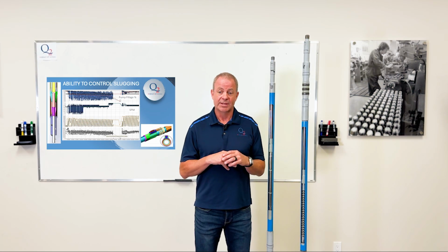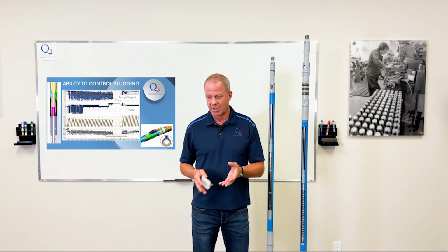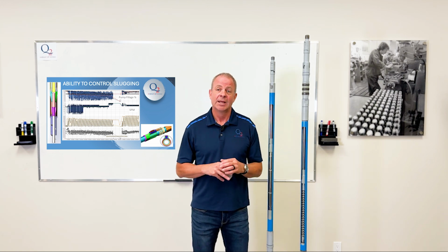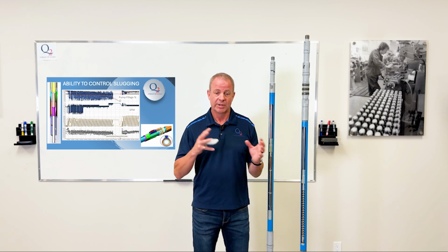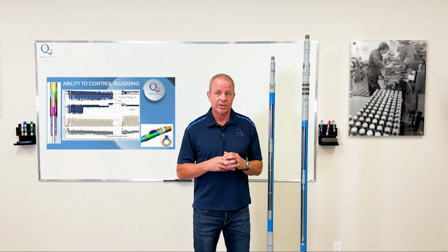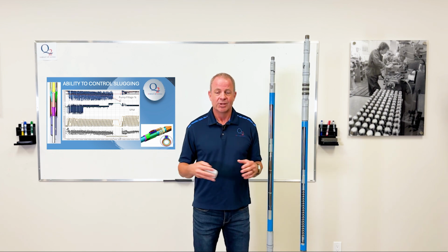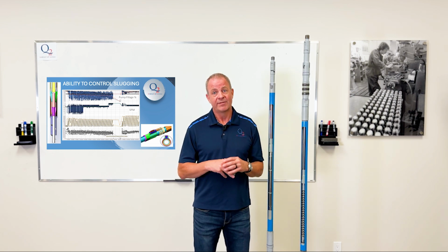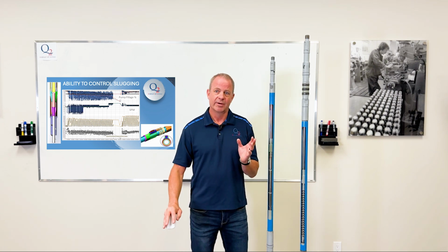With respect to the dog legs and how some of these wells have some curvature and some friction, you have to have a really experienced guy come on the rig to play with these parameters. It takes a few hours, but we've got a gentleman who does a very good job, and he can increase the instantaneous production by 20-30% just by modifying things on surface, if you have the right tools in the ground to begin with.